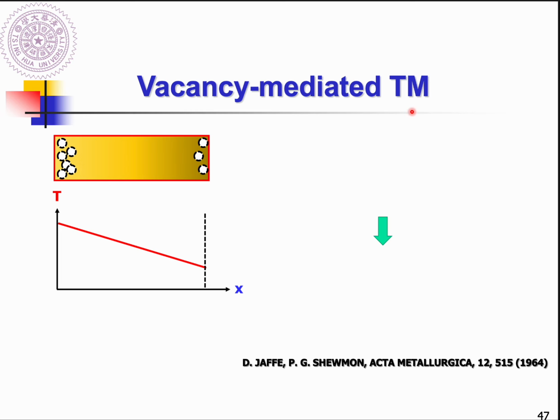In order to have a thermal migration phenomenon, as you expected, the temperature gradient here is definitely very high. Some people ask how high it may be to induce thermal migration. I can give you some scale, for example, roughly 10 degrees C per 100 micrometers, but slightly depending on different materials.